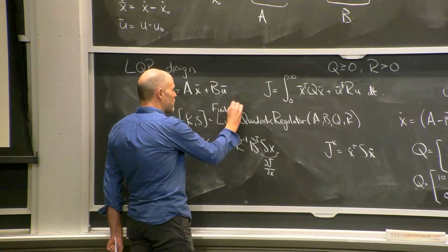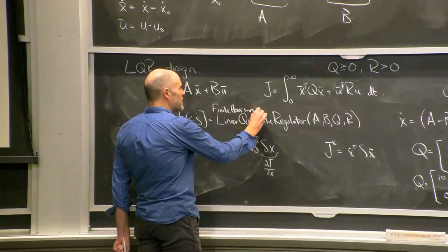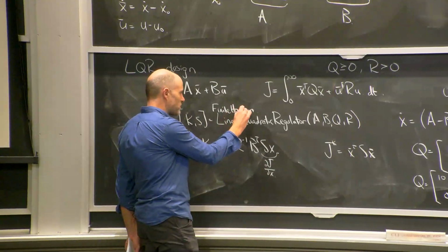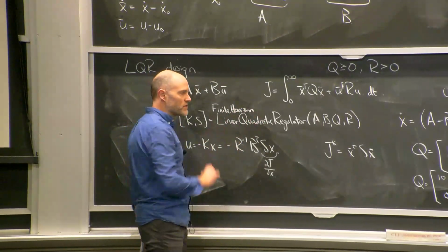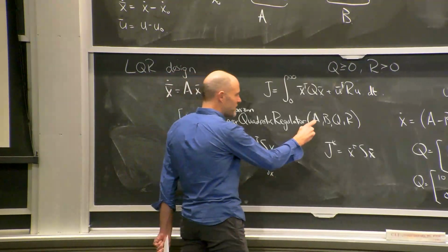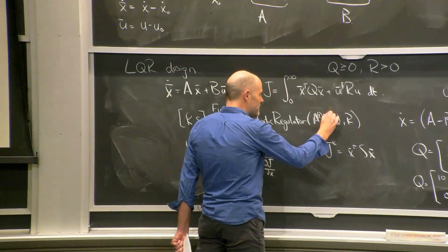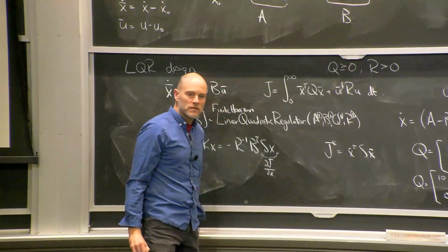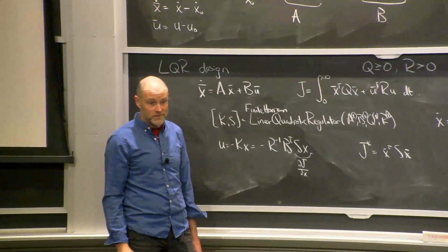There's a finite horizon linear quadratic regulator method in Drake and in some other packages, right? That does the general form of that. You get A as a function of t, B as a function of t, Q as a function of t, and these can be trajectories.